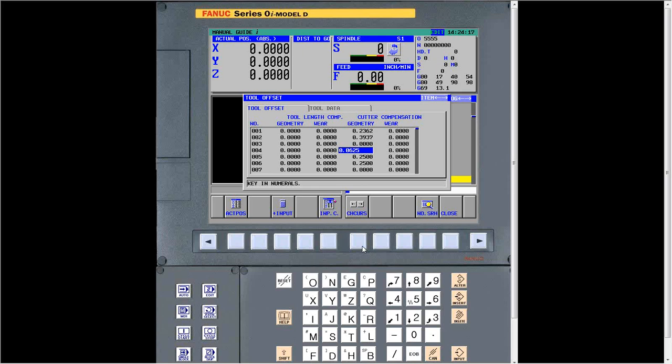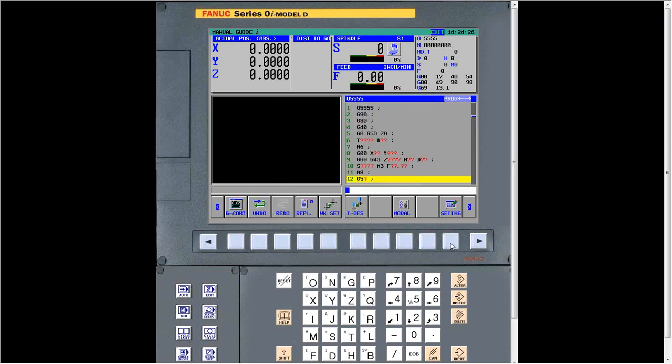It's made from high-speed steel, so it's going to be a little bit more forgiving. It won't break off as easily as a solid carbide. So we want to use tool number 4, but again, it's got to be either a drill or a ball nose end mill. So we're going to use 4, alter, then we'll position at 0, 1 inch again. Sorry, I know this is a little redundant, but it's good review.